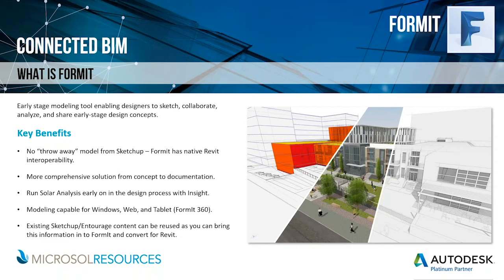FormIt allows you to open and import SketchUp files as if they were native FormIt files, including layers, groups, components, scenes, materials, all that type of information. And thanks to this, and as we'll touch on a little bit more briefly, FormIt can be used as a quote-unquote pre-flight tool for preparing SketchUp data to become something more BIM ready in Revit. However, of course, be warned, as the old adage goes, garbage in, garbage out. SketchUp models still need a certain level of cleanliness to successfully get the geometry into Revit, but I'll show you a couple of those tools here to help with that process.